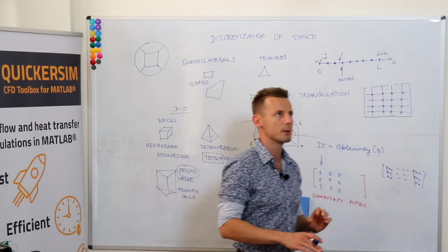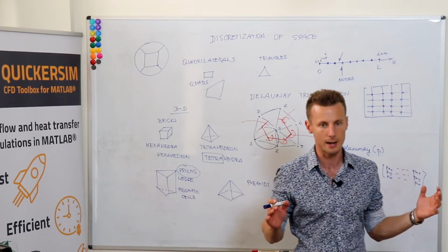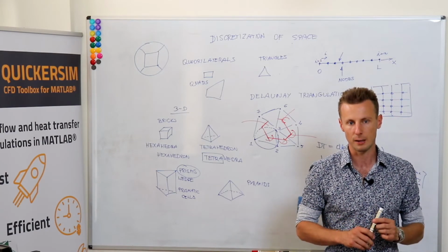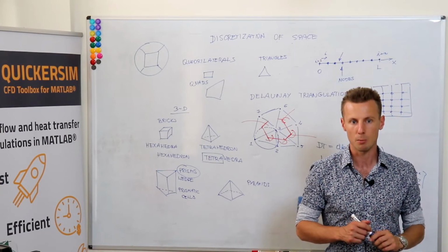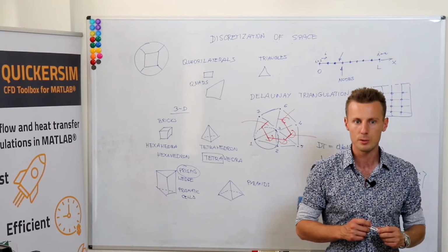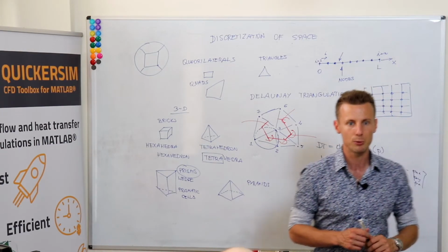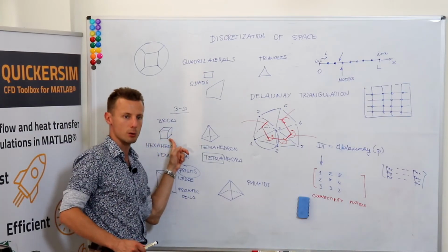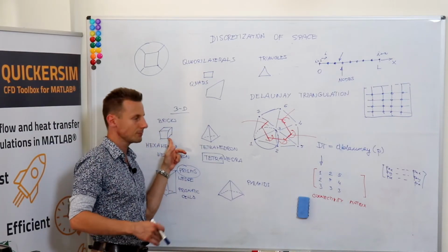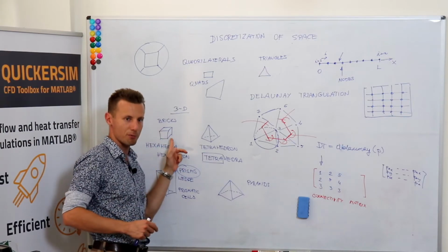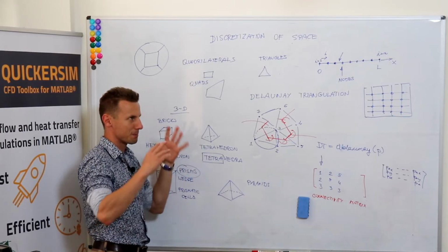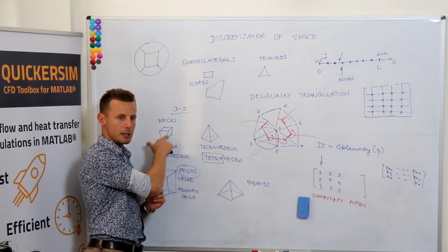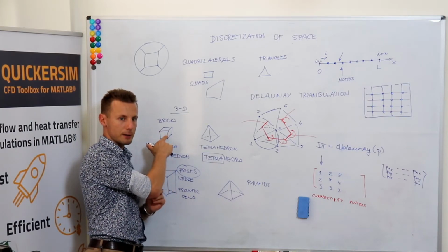If you subdivide the whole space into hexahedra, you end up with the smallest number of finite volumes, so basically the smallest number of unknowns in your system. If you want to subdivide one brick into tetrahedra, it takes a couple of minutes of focusing on spatial imagination, but believe me, you subdivide it into 6 tetrahedra.